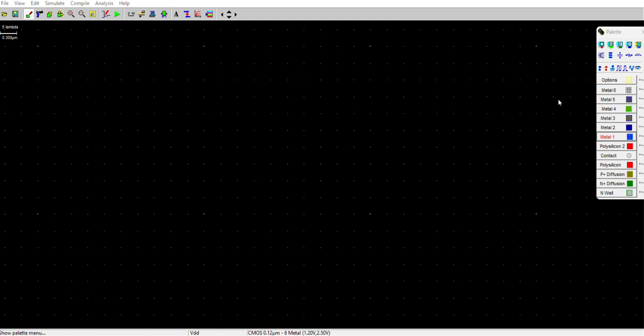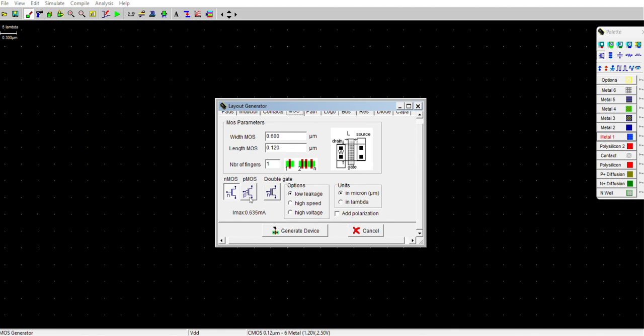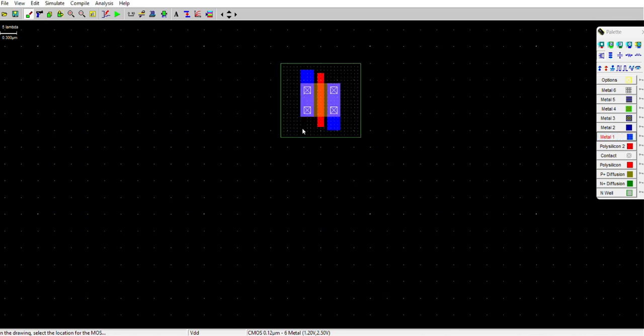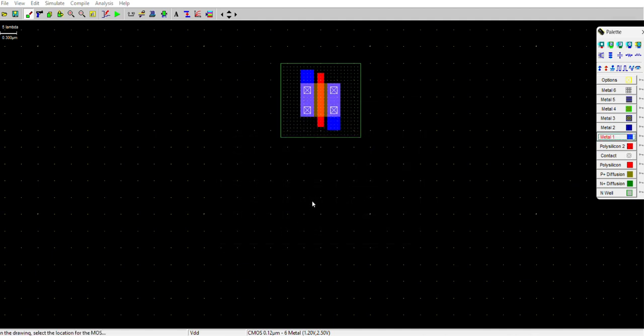In this section we are going to make a transistor based model design. This is very easy. We take a PMOS from the palette of layers. We take a PMOS, then we take an NMOS, we connect the polysilicon layer and we connect the metal layer. Then we will apply our VDD, ground, output and clock pulse, and we will look at the timing diagram, and that's it.